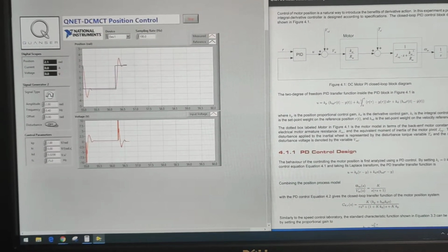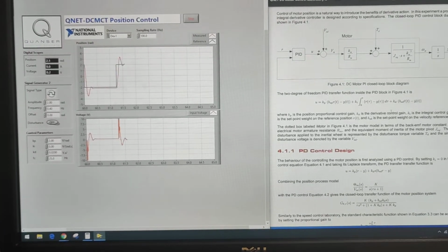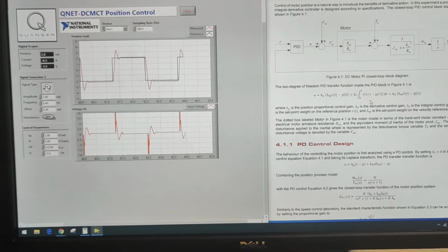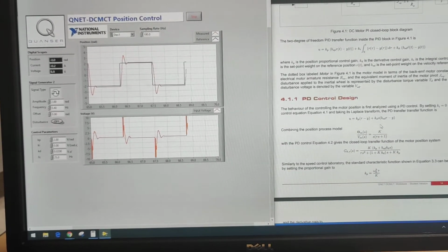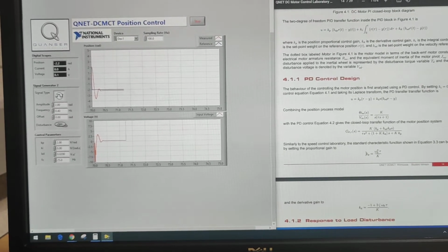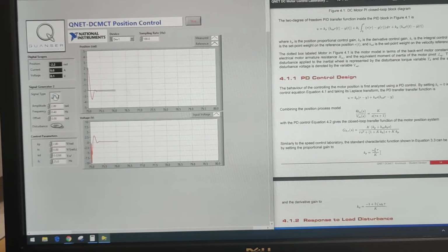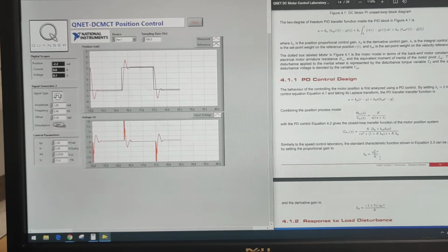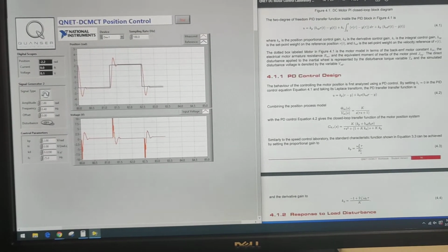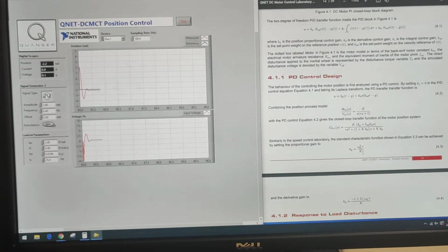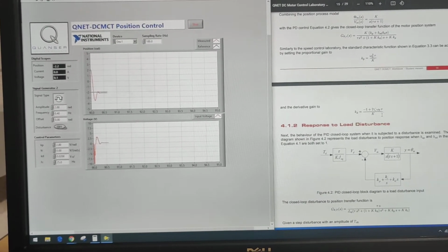Okay. And this is the model of the PID controlling transfer function, basically still a transfer function in time domain. The PID control can be modeled as such, and the Kp can be calculated as this. This omega 0 will be given in the next few sections, and this tau and K are the parameters we measured in lab 6, the DC motor modeling. And this Kd can be computed as this.